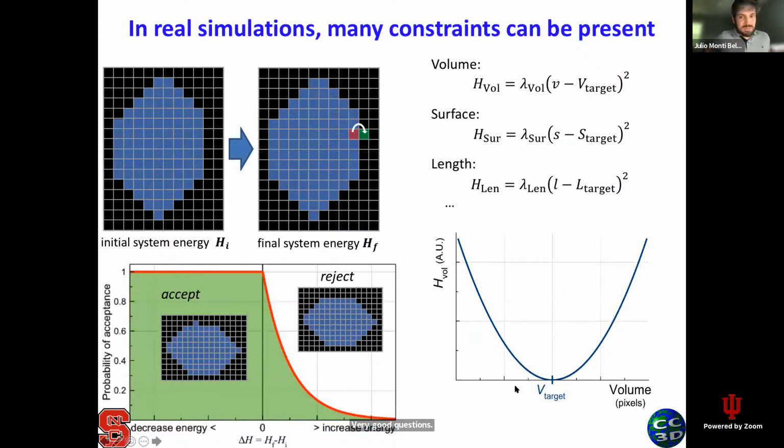The way to convert between pixel sizes, that's a choice that you make right at the beginning. You choose, okay, do I want to represent my cell with 10 pixels, or do I want to represent my cell with 100 pixels? So that's going to be your choice. Okay, what is going to be the resolution of our system? But you cannot do that midway in the simulation. No.